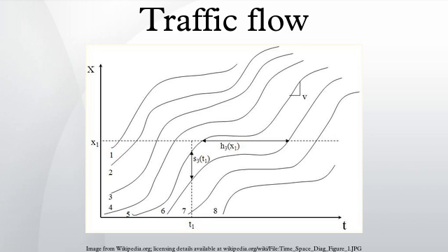Applications. The Bottleneck Model. One application of the N-curve is the Bottleneck Model, where the cumulative vehicle count is known at a point before the bottleneck. However, the cumulative vehicle count is not known at a point after the bottleneck, but rather only the capacity of the bottleneck, or the discharge rate, μ, is known. The bottleneck model can be applied to real-world bottleneck situations such as those resulting from a roadway design problem or a traffic incident. Take a roadway section where a bottleneck exists such as in Figure 12.